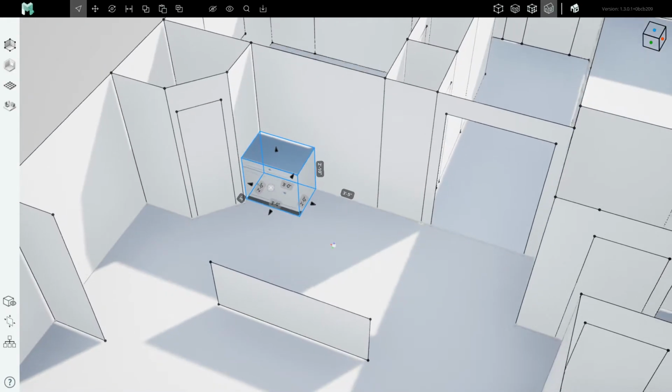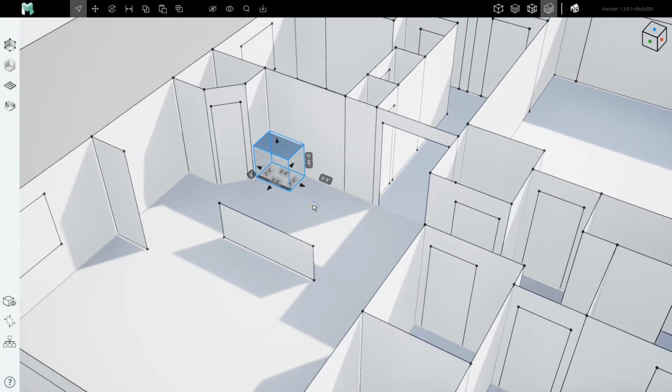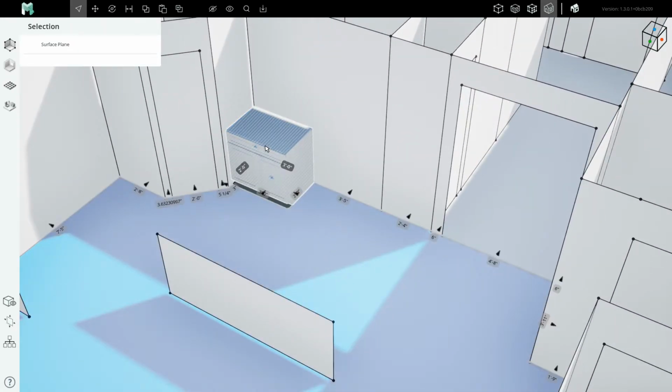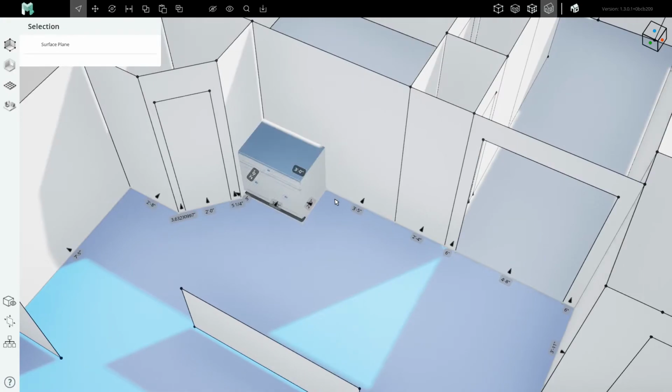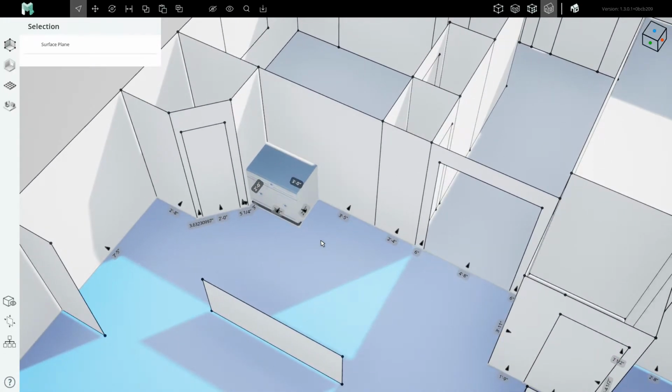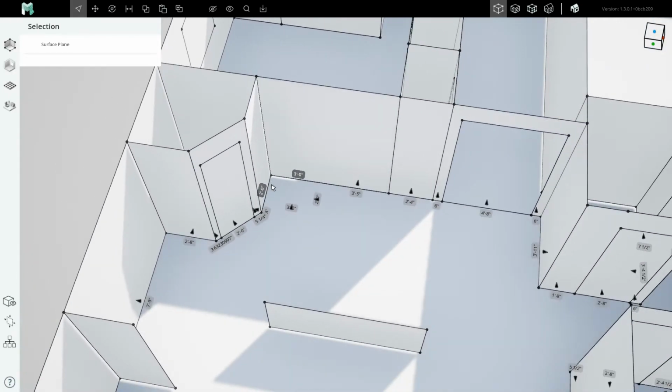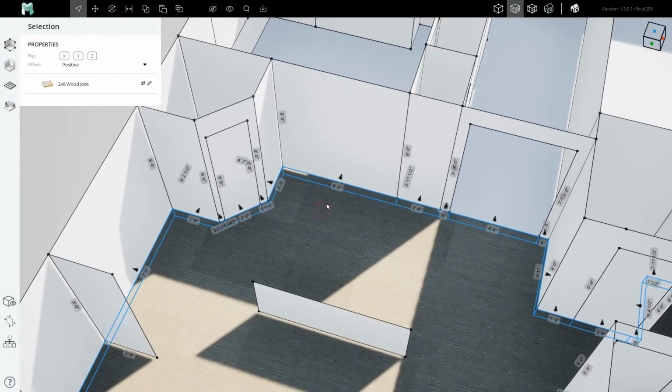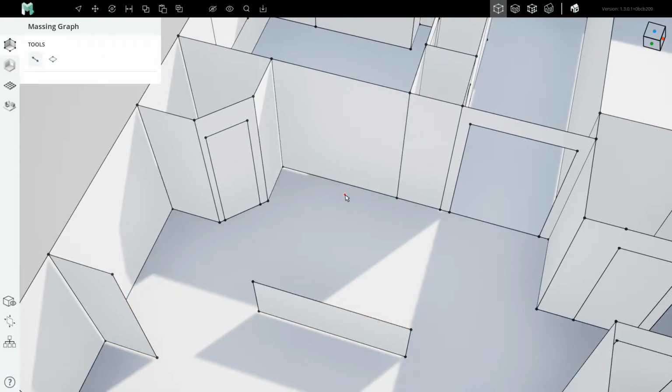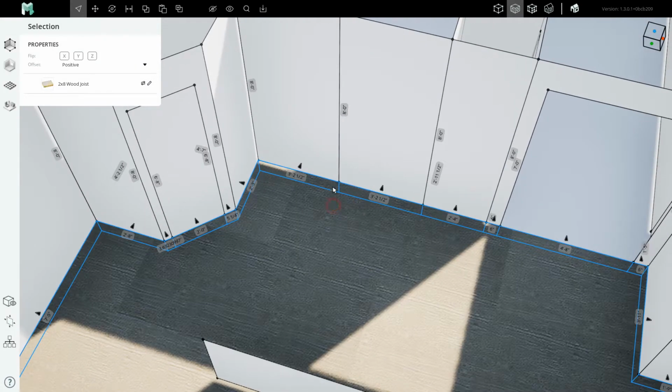It's really fast. It's a bit fragile because when the surface graph that you've placed this cabinet on ever changes, such as it thinks of its edges as being one continuous surface graph edge from here to here, and if I use my massing graph and split the floor that it's attached to with an edge such as this one, it adds a new vertex to this floor.